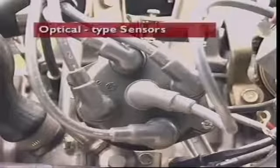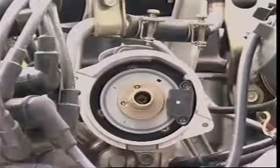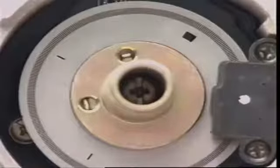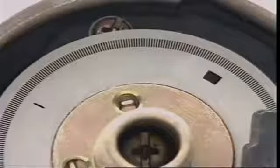Crank angle position and engine RPM can be detected optically. A signal rotor plate is attached to the distributor shaft. It has 360 slits at 1 degree intervals on its outer edge. Inboard of the 1 degree slits are 4 slits, one for each cylinder.